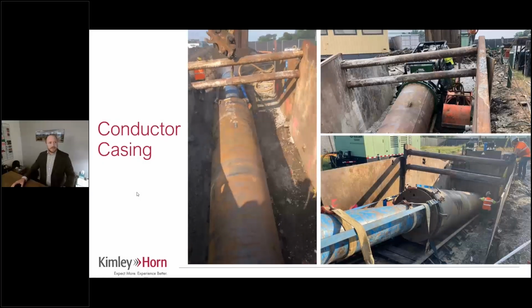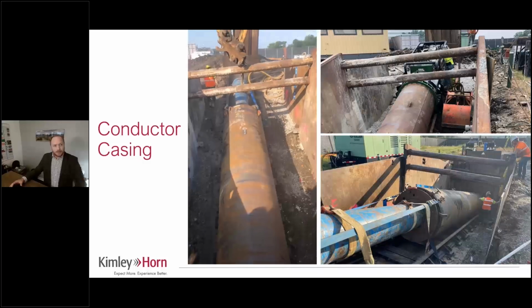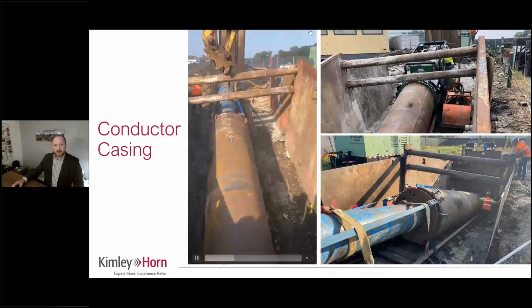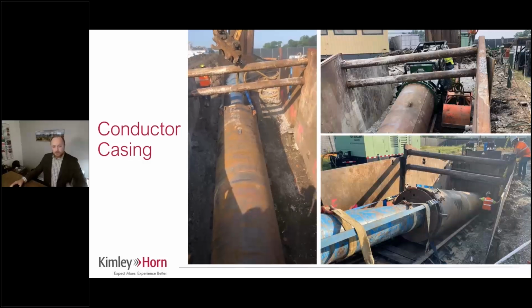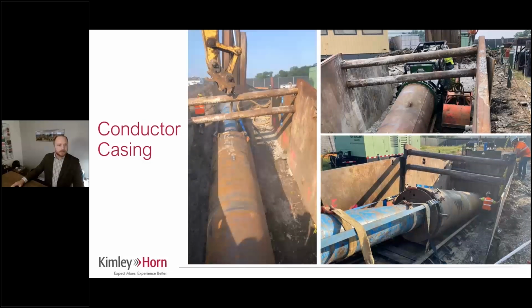And then, I hope you can see, there's a video looping on the left side showing an air hammer strapped to the back of that casing pipe. On the right side, you can see there's an auger machine. As that casing pipe advances through being rammed in place, the auger then augers out the soil that's taken in.